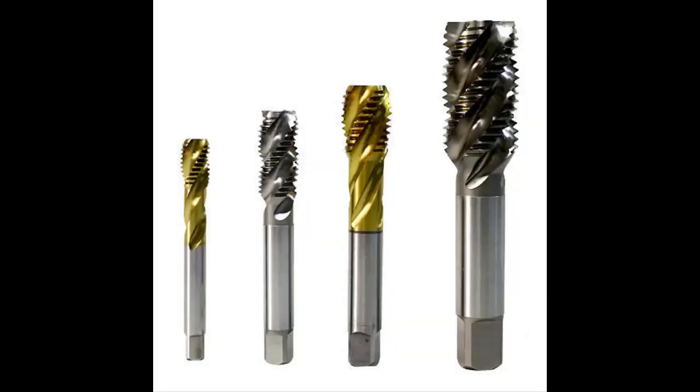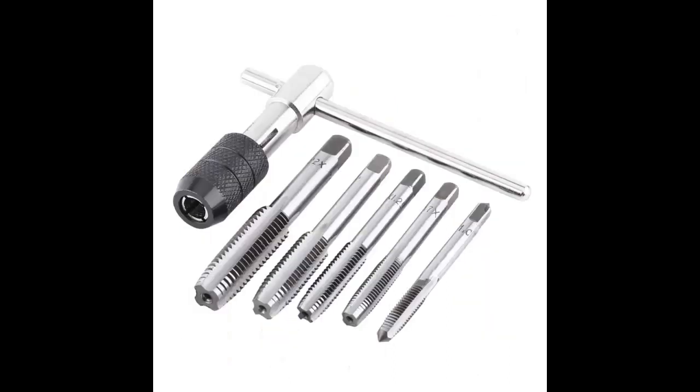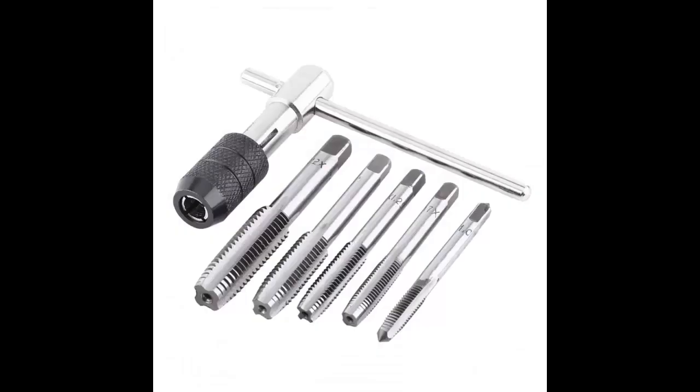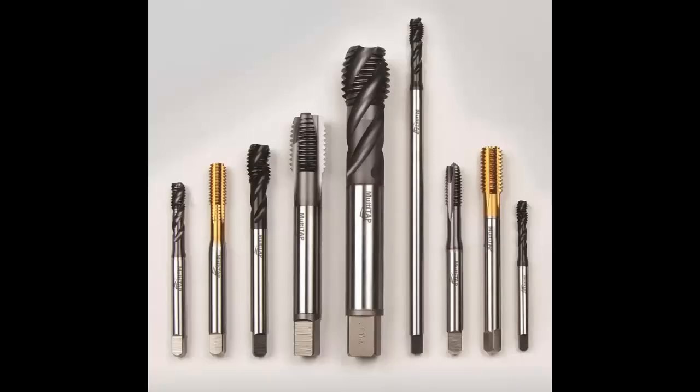A tap is the cutting tool for tapping, wound down into a hole, and cuts a thread as it goes. There are many types of tapping tool. Choose the right tap based on what type of hole you want to thread. The taps can be divided into hand taps and power taps. Hand taps are the most common tap types, including taper tap, bottoming tap and plug tap. Power taps are the types you should choose for CNC applications or manual machining work, including spiral point tap, gun nose or bull nose tap, spiral flute tap, gun tap, form or roll tap, and more.